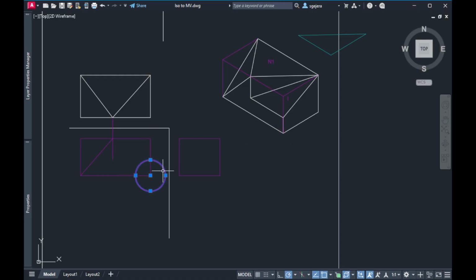Or another way, para hindi ko na kailangan i-measure, I know this one is parallel to this line. So since I know that this is parallel, then it must mean, kasi all parallel lines or lines that are truly parallel will always appear parallel in all views. So pwede actually ang gawin ko is just make a parallel like so. And you can make shortcuts like that, no? That will increase your productivity or your parang workflow or pace.